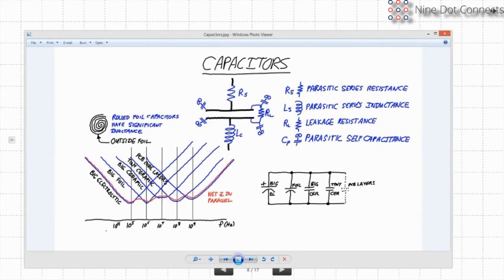And that's what you're trying to do when you put capacitors into a circuit. Back when everything was small and TTL, everybody always put in a 0.1 microfarad, and they put in hundreds of them. But as speeds went up, those capacitors were no longer good for the high speed. When you have stuff switching in the gigahertz region, a 0.1 microfarad is almost no good at all. So it's important to understand the different things you have.